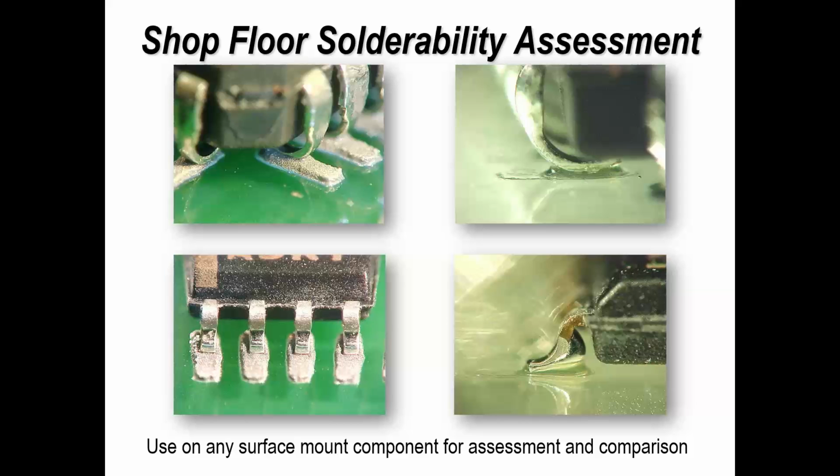So is it any different? Has it suffered from the baking process at all? If the answer is no, then fine. That vindicates you baking the components for 10 hours, 5 hours, at whatever temperature you've decided on, and gives you confidence in those components. So that's a simple thing. Yes, you're going to use up 2 or 3 components, or maybe 5, but if they solder, I guarantee they'll probably solder again when you add them to the board on the assembly.